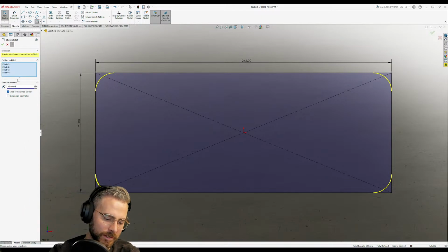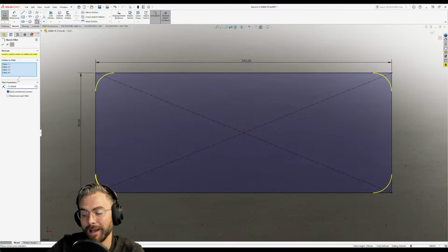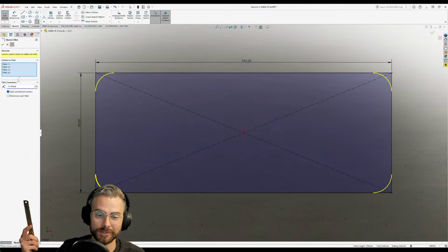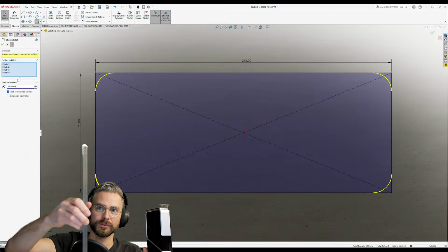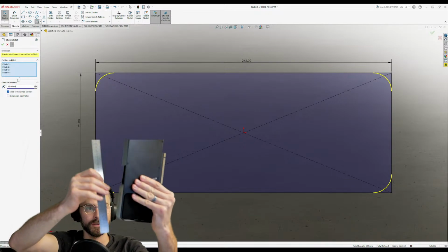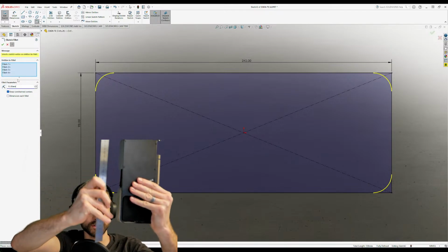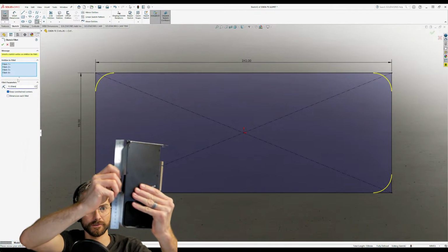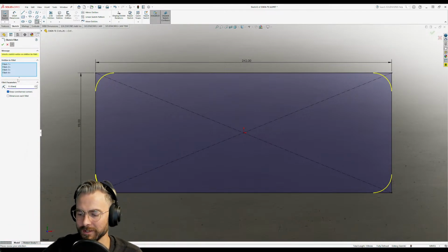Edition are 15 millimeters. The way I figured that out is I'm measuring this in a very sort of janky way. I've got a metal ruler here which is relatively straight, and you've got a relatively straight edge here. I set it on a flat surface, straight edge to straight edge, and then I just looked at what dimension I couldn't see daylight through. That's where the end of the radius was. So that's how I measured the radii on this, and they're all 15 mil.